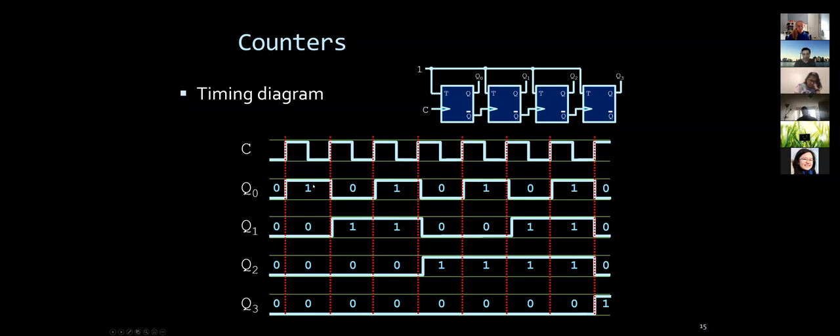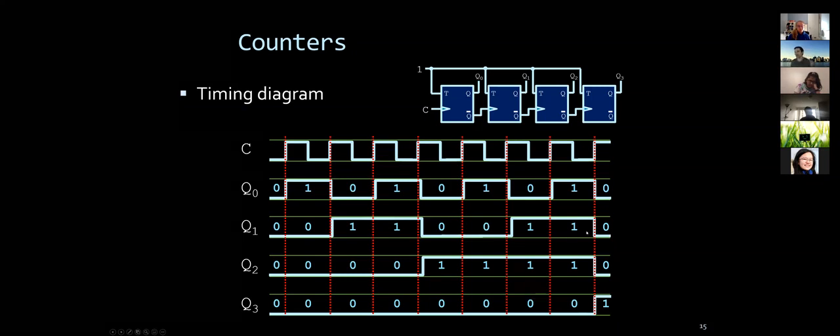So, again, use your imagination, look this way, right down. These, all zeros, 0001, 0010, 0011, doesn't that remind you of something? We just encoded all the binary 4-bit values, right? And they all go one by one. So essentially, this T flip-flop just increases the value.